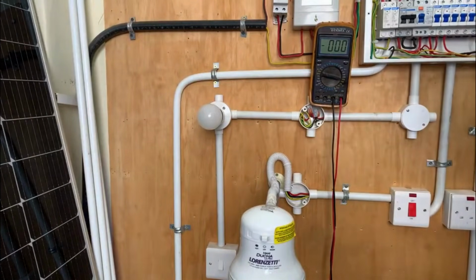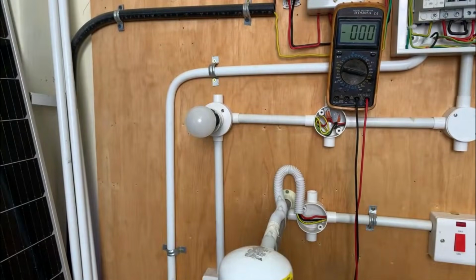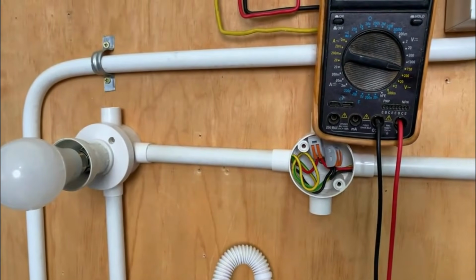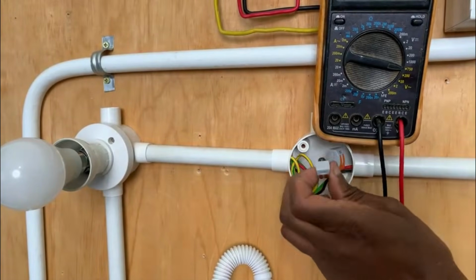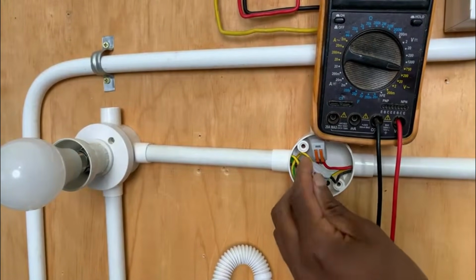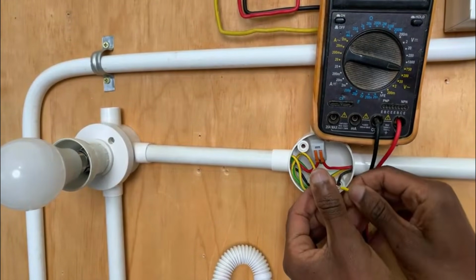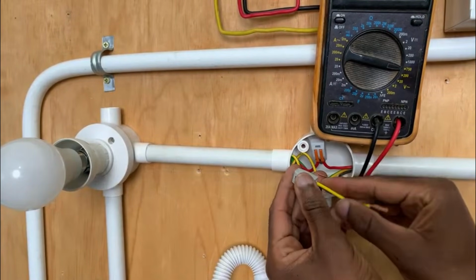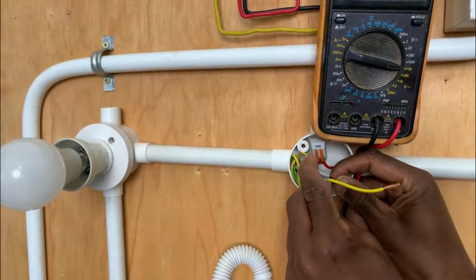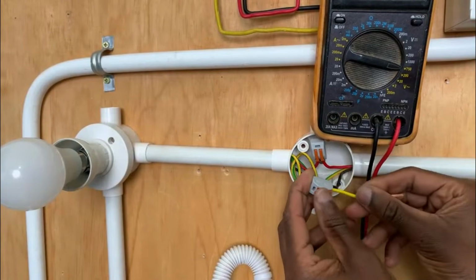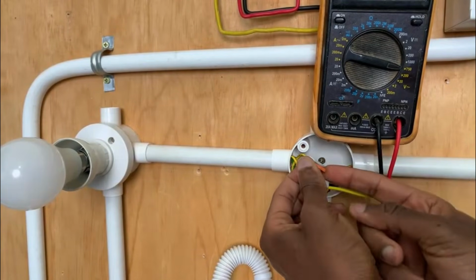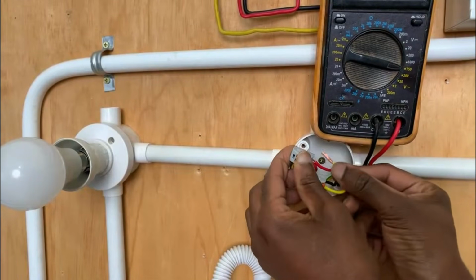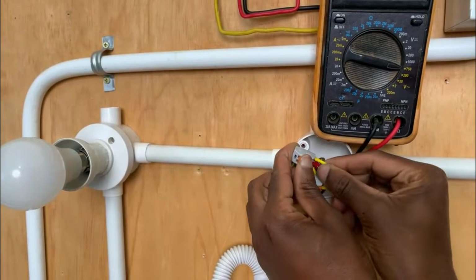So in order for me to come up with a problem, let me come up with a problem, isn't it? My circuit, remember, it's off. So to come up with a problem, I will short circuit the line and the neutral. I simply lift one of the legs like that, insert it in. I want to force the two of these cables in. I don't need to really have it go all the way, but it's there, right? And then for this other one, I want to do the same. Remember the MCB. Don't try this at home if you are not sure about what is happening. The MCB is off. Insert it.